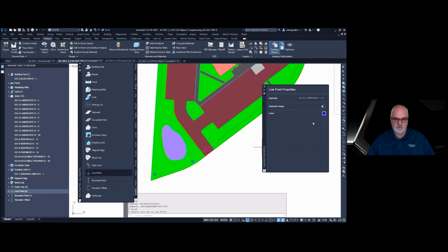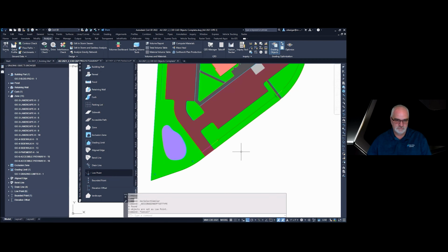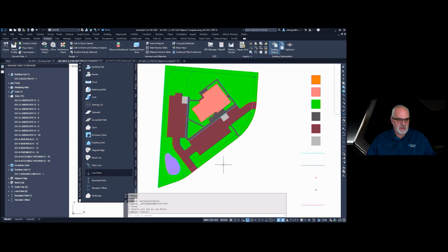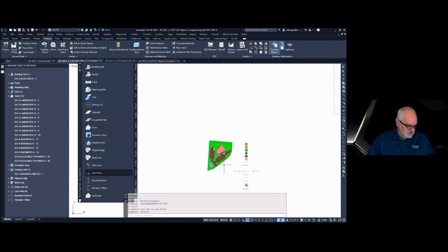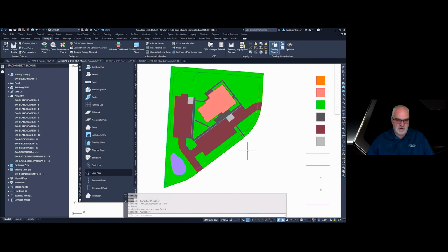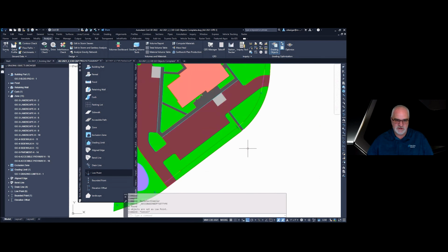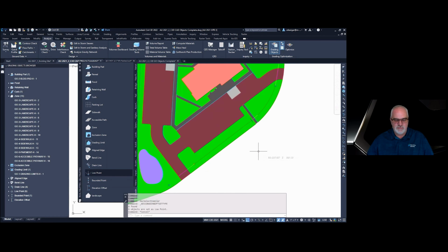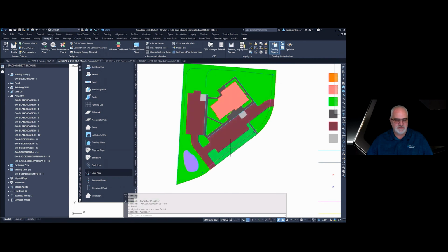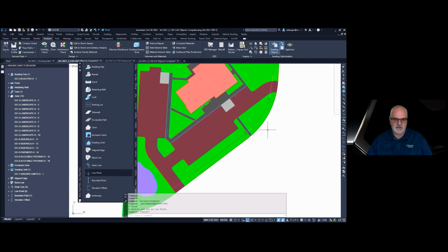And no elevation given. So you just keep defining each of these grading objects and doing your best to define things. Keep in mind, you don't have to be perfect the first time. Bring something into Geo and then see how it works. And if you have to, come back, adjust it in here, and then send it back to Geo. It may take a couple times, and it takes you a few times of assigning these to kind of get the gist of planning and things like that.